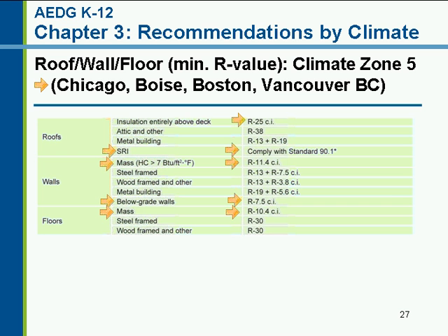For the floors, mass floors, another step up here to R10.4 continuous insulation. Steel framed and wood framed floors are R30 continuous insulation.